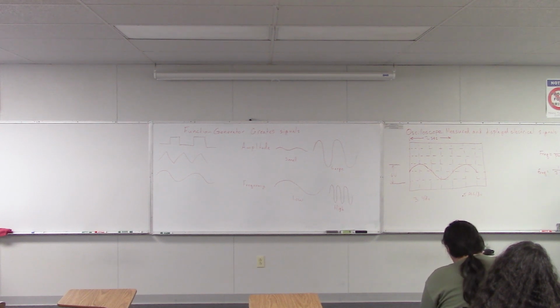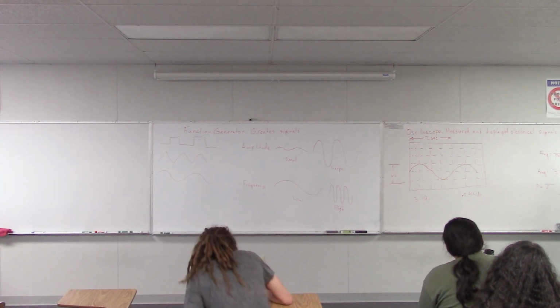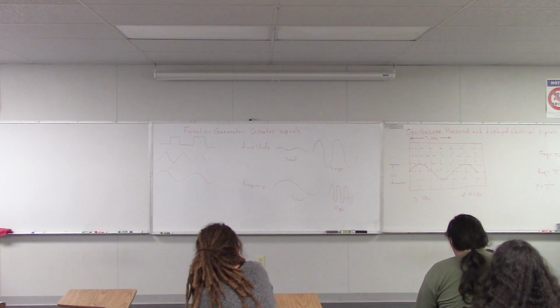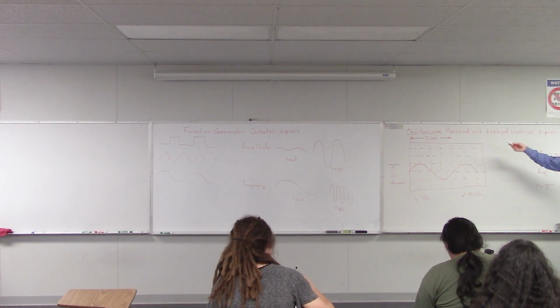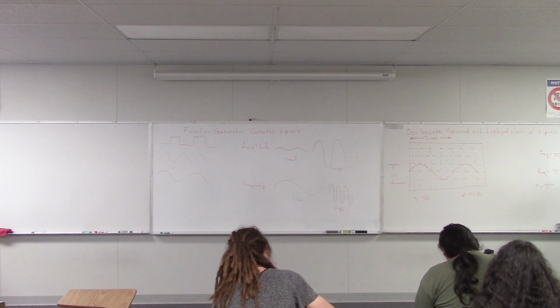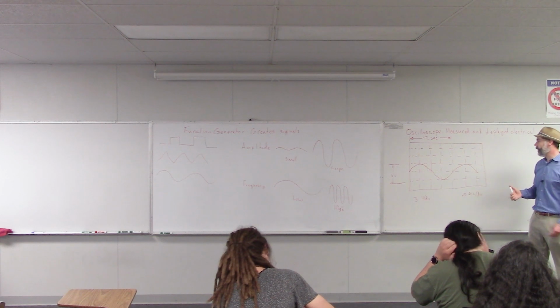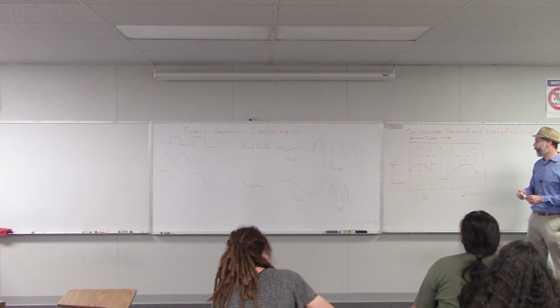And if we know the frequency, we could calculate the period also. We have another formula for that. We would just say period is 1 over the frequency. Okay. So that was kind of what we talked about last time. So the oscilloscope measures the electrical signals. You can zoom in and zoom out, and you can use these divisions to help you get approximate measurements.